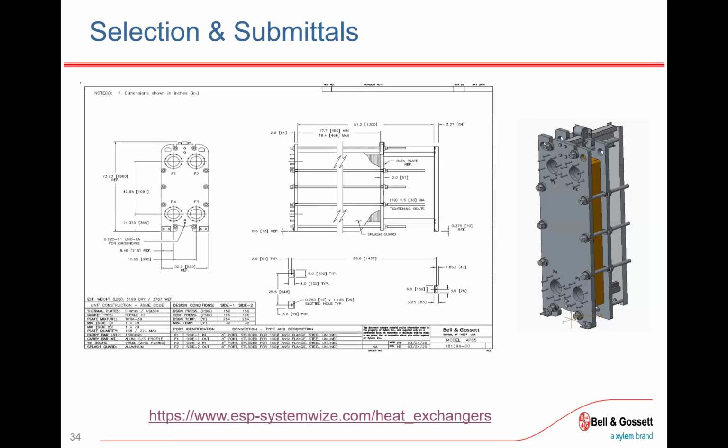Coming into this, I was like, wait, what's going on? Yeah, I'm not aware of a benefit. I'm sure there's probably something in some industry with some gradual temperature change, but in that case where you take the hottest and coldest and they're ending at the same point, giving that greatest LMTD, holding the surface area constant would give you that heat transfer rate. I think it was like 25% greater, or a reduction if you were to do the parallel flow.